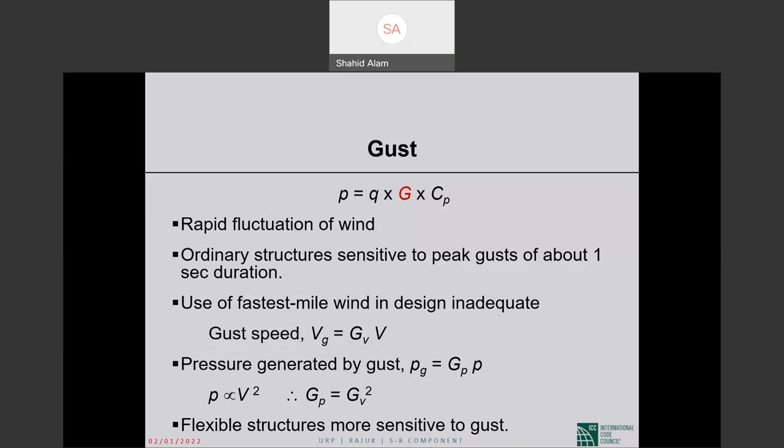The shorter the averaging time, the higher the average wind speed. So when the averaging time was that long, 30 to 60 seconds, the average wind speed was lower. I told you a short time ago in AC 705, most of the United States has a basic wind speed of 90 miles per hour. That number back then, when we used fastest mile wind speed, was 70 miles per hour, to give you an idea.